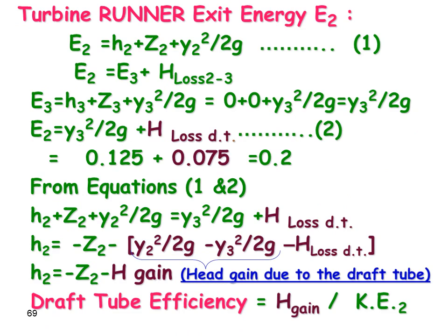What is the function actually of the draft tube? What happens at section 2? Let us go again and get Bernoulli's equation or energy equation between point 2 and point 3. We can find that E2 equals E3 plus H loss from 2 to 3, and E2 equals Z2 plus H2 plus V2 square over 2g.